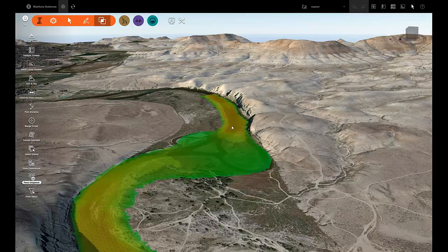And right now, obviously, this is just a model builder terrain model that has a wonderful visualization because of the elevation that we have. But any of the grading elements, whether that is a road, a bridge, whether you've grabbed the coverage area, manipulated that, gone to Civil 3D, created a terrain surface, imported that into InfraWorks, you have that ability to run that model against those results.